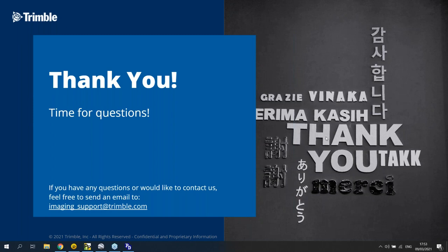No, unfortunately not. The processing engine behind the data that comes from mobile mapping systems is different from the processing engine in TBC. You process your trajectory in POSPac, and this is different from processing your raw GNSS measurements that come from the R12 in TBC. So the engines are different and the behaviors are different.